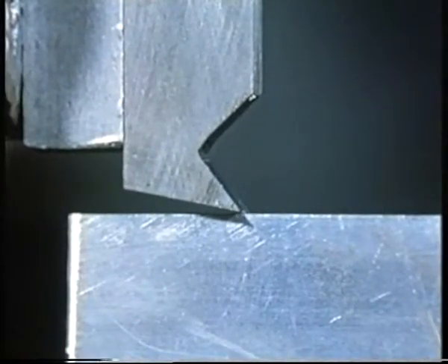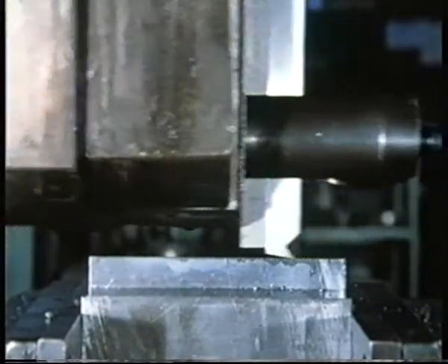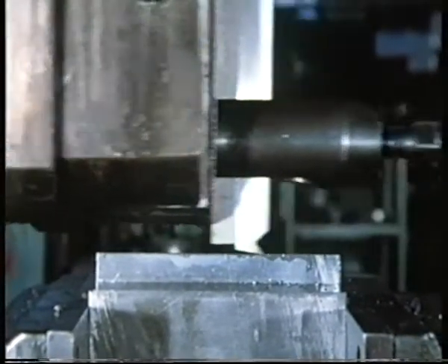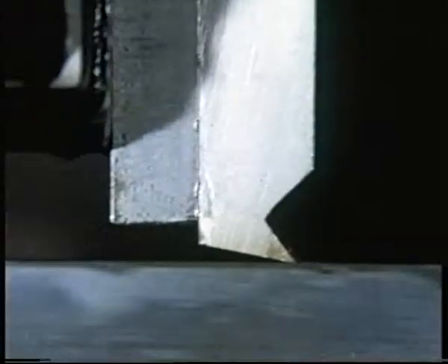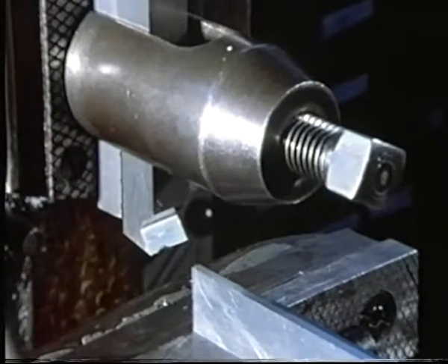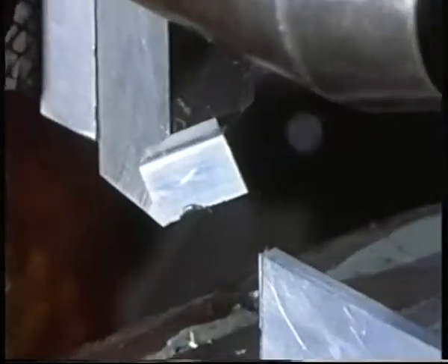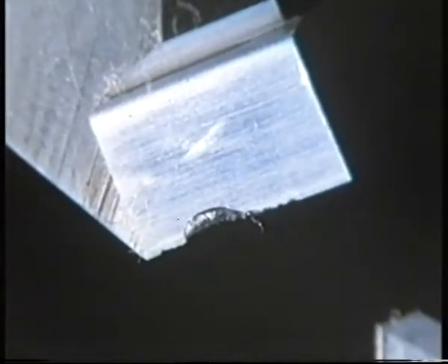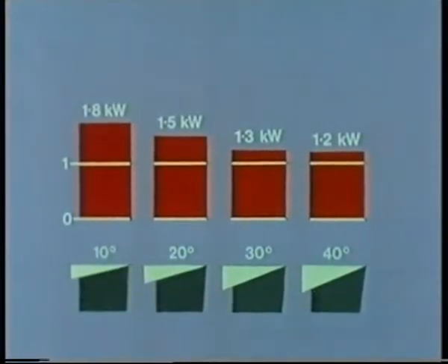But just how serviceable is a tool like this? After only a few moments' use, the cutting edge is damaged. Damage like this is expensive, so is excessive power consumption. So this business of choosing the right angle is very important.